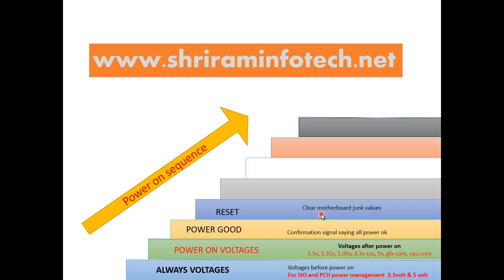A motherboard is a combination of lakhs of MOSFETs. So the reset signal clears all the junk information on the motherboard. It clears the RAM, clears the CPU, clears everything on the motherboard and keeps it ready for work. That signal is called the reset signal. There are 2-3 resets. One is called the PLT reset, the platform reset. Another is called the CPU reset. Then the PCI reset.